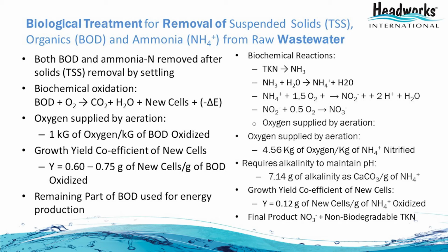So as you can see, in the nitrification reaction there is a net production of hydrogen ions, or acidity. That's why nitrification reactions tend to depress the pH, because hydrogen ions give rise to acidity of water. It depresses the pH, and in order to counteract that, you have to add some alkalinity, which neutralizes the acidity. Now, many wastewaters, or the majority of wastewaters that come into the treatment plant, do have some buffering capacity in the form of alkalinity. So then the acidity can be neutralized by this buffering effect of the alkalinity. If not, then you have to supplement the alkalinity.